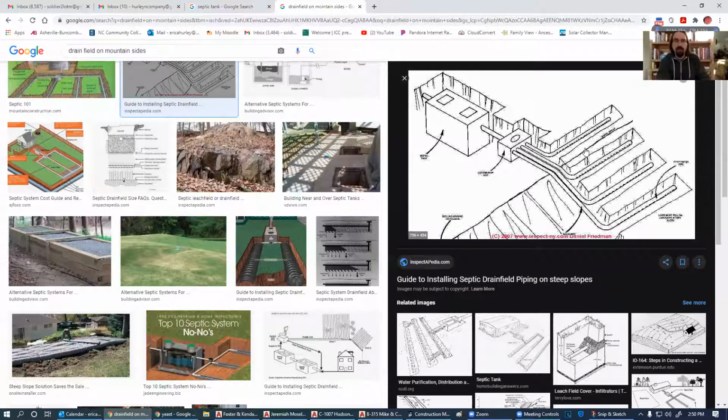I suppose so. I know there are going to be some situations where you're going to have to drop more than a 1/4 inch per foot to stay under grade, because grade's going to drop steeper than that. Okay, you're right, I'm sorry. This has to be a 1/4 inch per foot. This has to be a 1/4 inch per foot. This does not have to be a 1/4 inch per foot, because you don't have to deal with the waste. Got it, sorry, I told you wrong.